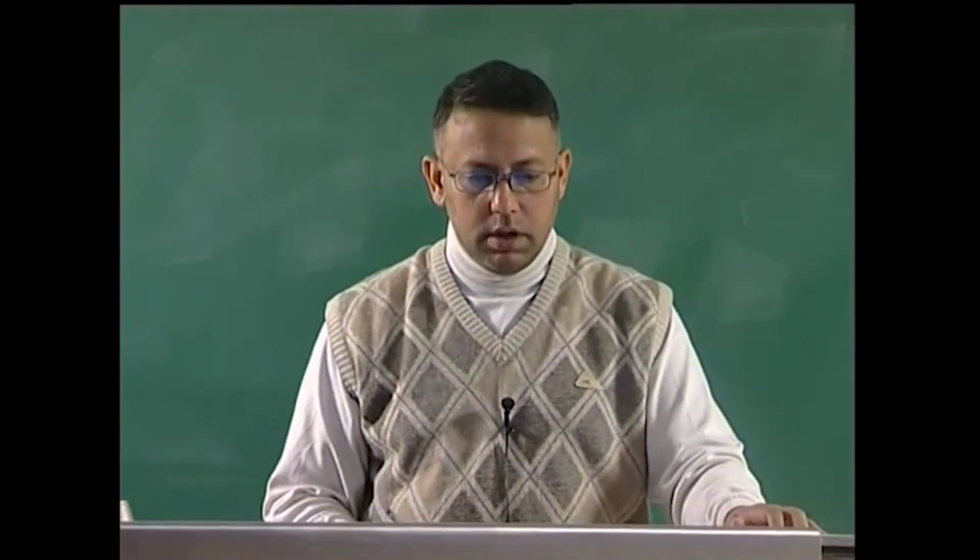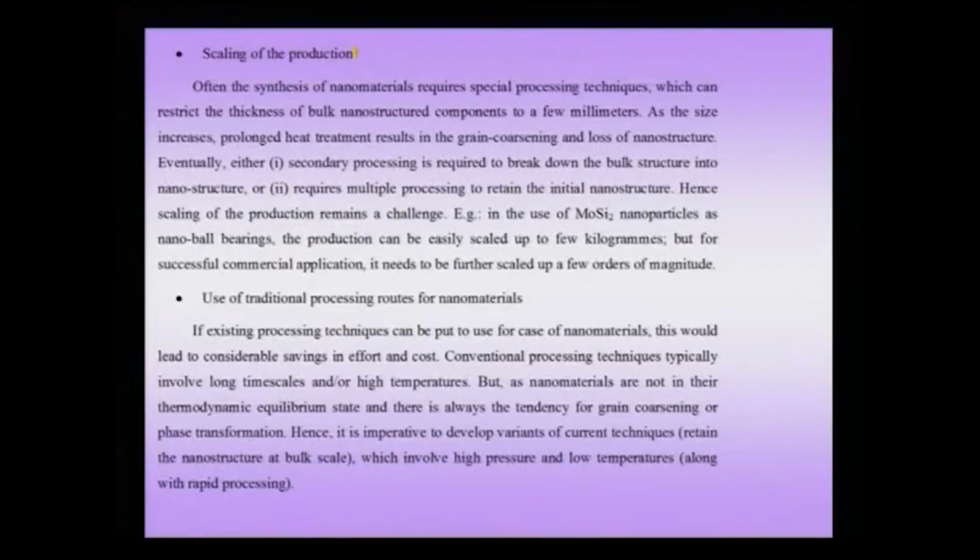So, a further challenge which we need to address is the scaling of production. Often synthesis of nanomaterials requires special processing and techniques which can restrict the thickness of bulk nanostructured components to a few millimeters. As the size increases, prolonged heat treatment results in grain coarsening and loss of nanostructure. Eventually, either secondary processing is required to break down the bulk structure into nanostructure, or we require multiple processing to retain the initial nanostructure. Hence, scaling of production remains a challenge.